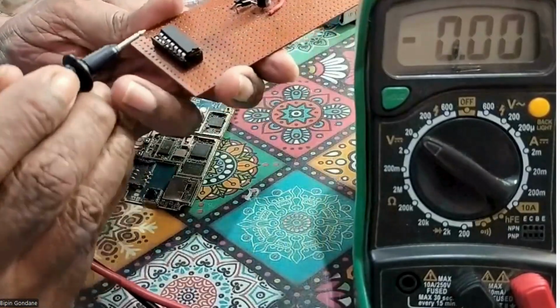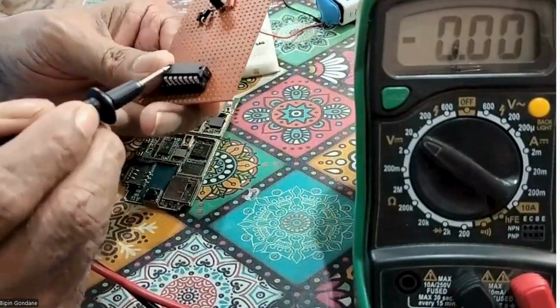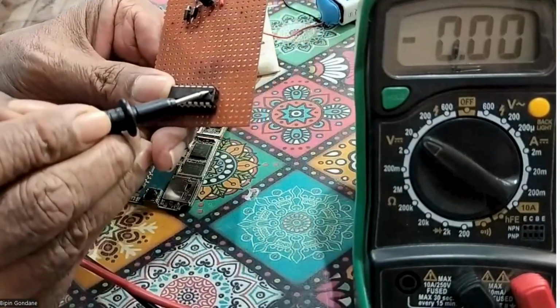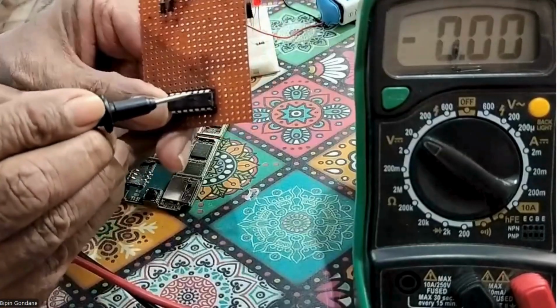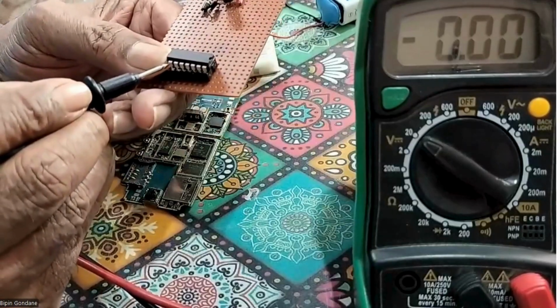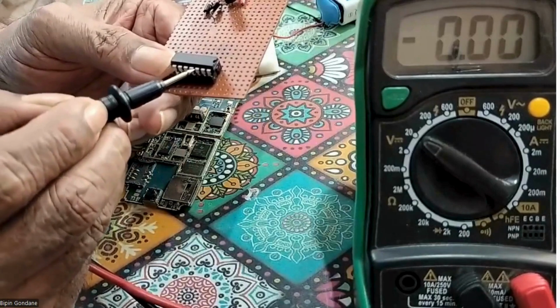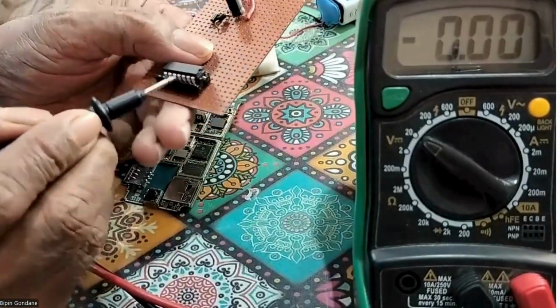How many pins is this? A 14-pin IC. The base is a little bigger, but I just wanted to show it to you. Right here also you have a notch, so I said left hand side is pin number 1, 2, 3, 4, 5, 6, 7. Then 8 comes over here, and then 9, 10, 11, 12, 13, 14. So you can see the bases are different and this IC is different.